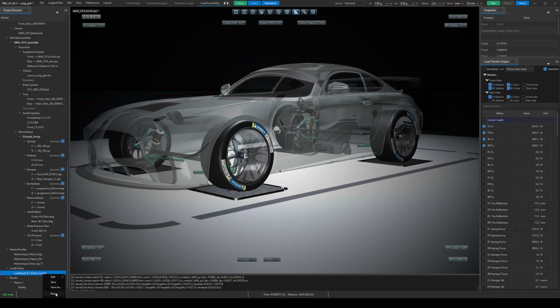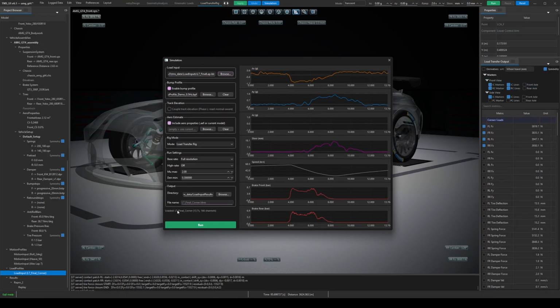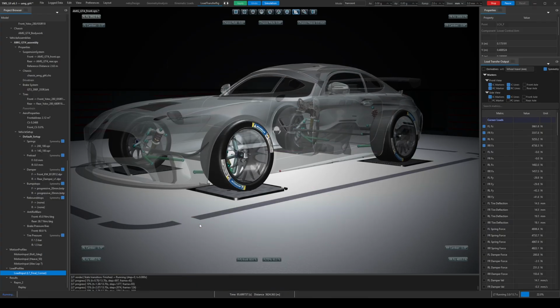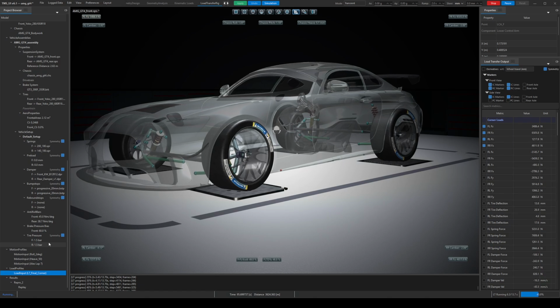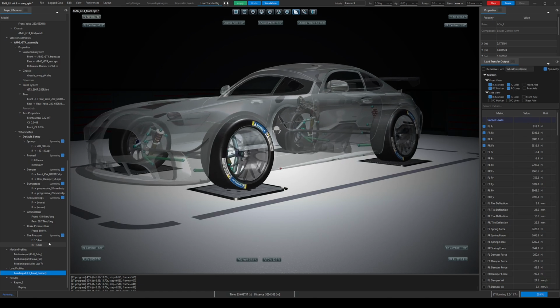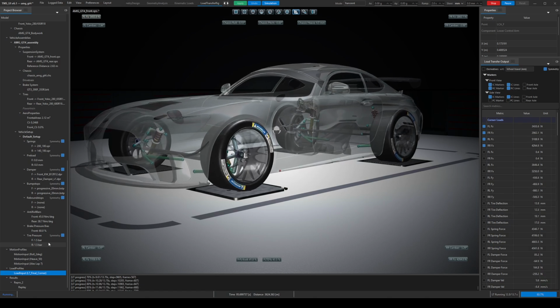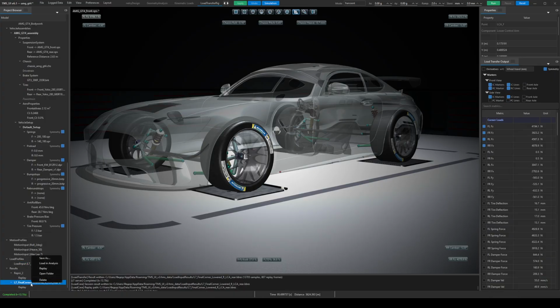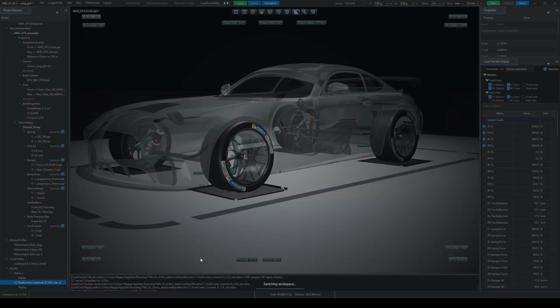To me, this damper position discrepancy after throttle application looks like the modeled rear suspension has more anti-squat than the physical car had when the data was recorded. As an experiment, I lowered the front attachment point of the rear lower A-arm and reran the simulation. The correlation immediately became much closer.